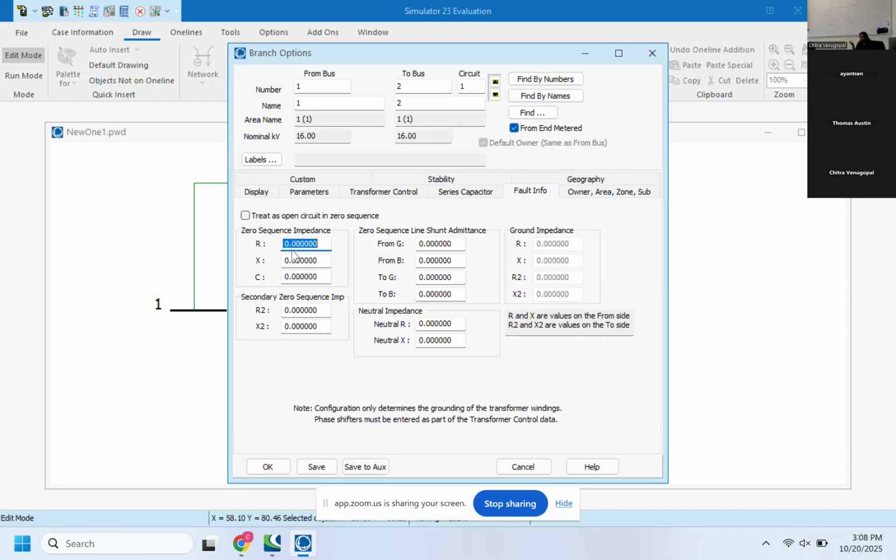So we always provide a metal rod at the ground and provide it with a wire and connect it, so that the wire and the rod can provide a lower impedance path for the fault current to flow through it. Okay. So how much is the impedance that the metal and the wire together are providing the ground, the metal and the wire which are connected to the ground? What is the impedance of that? That is what it's asking here.